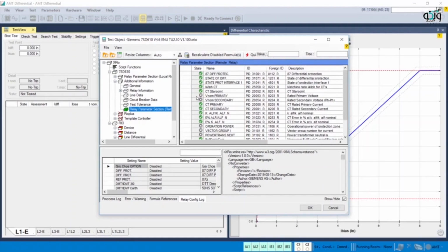This information can be entered in 2 ways. If the file of the relay is available in the DIGSI software, the information is imported from the software. Otherwise, the other person in post B should read this information from the relay and announce it. After entering the information, the characteristics of the curve of the relay will be created in post A. The same steps are taken from the Import from List point to the end in post B, and in the Additional Information section, the relay information of the post A must be entered so that the curve is created in post B too.